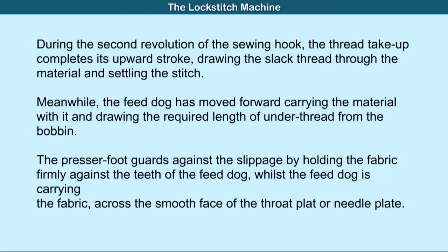The pressure foot guards against slippage by holding the fabric firmly against the teeth of the feed dog, whilst the feed dog is carrying the fabric across the smooth face of the throat plate or needle plate.